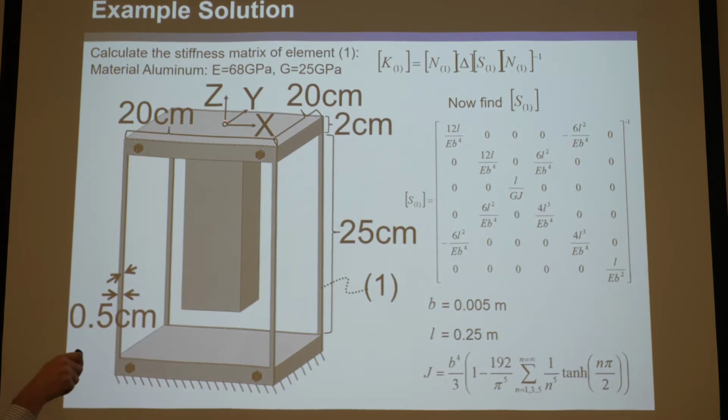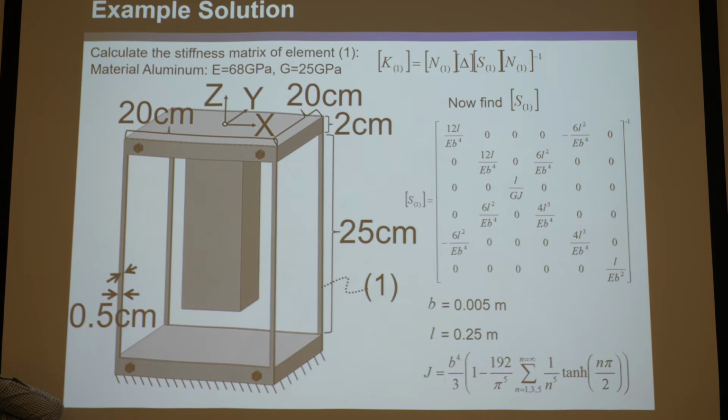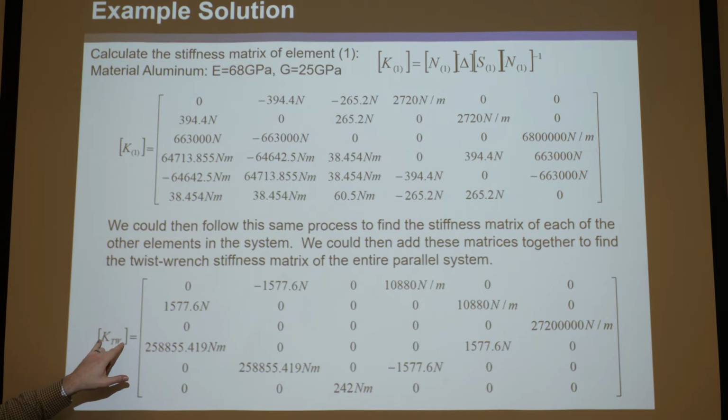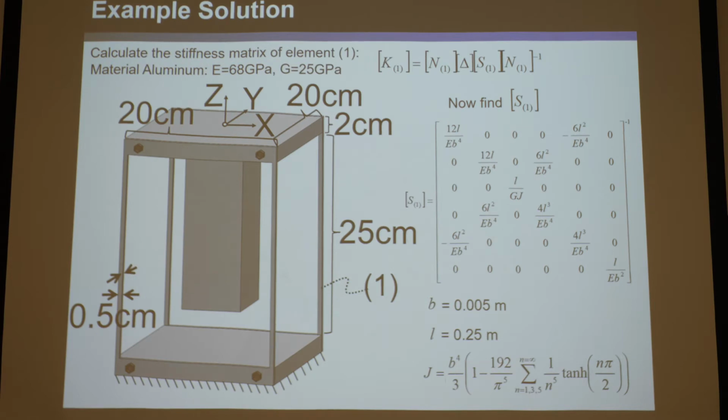If this global coordinate system were down here or anywhere, it would be telling me the 3 rotations and 3 translations of wherever you put it. I conveniently put it up on the top here though, because that's probably a point you care about and it makes the math easier. And by the way, if you did a displacement load on it, you wanted to put a displacement twist on it, say you did 3 rotations there and 3 translations there, and you put those together in a twist vector, then you could just multiply that by KTW. So KTW times T, and then out would come the wrench, the load that would need to be put on that stage, defined with respect to this global coordinate system, to move it that way.